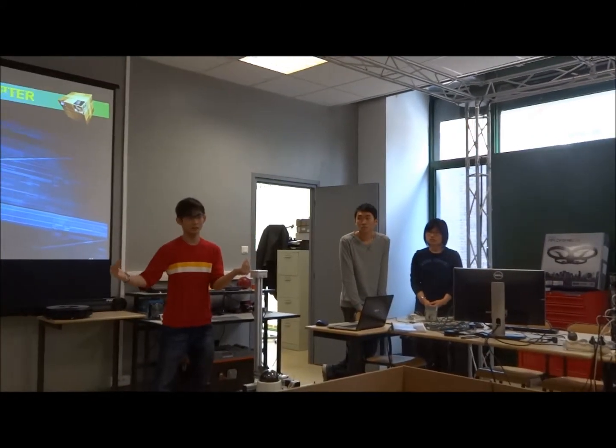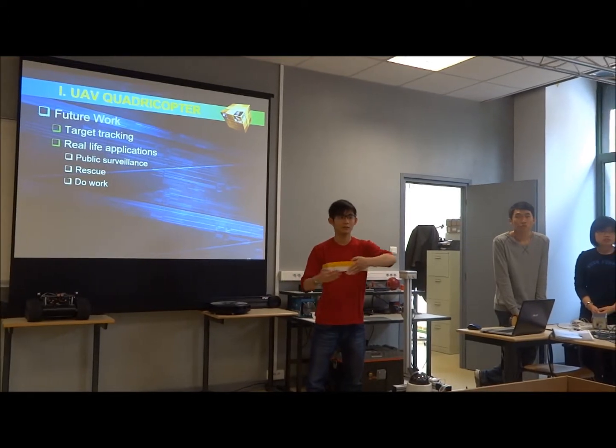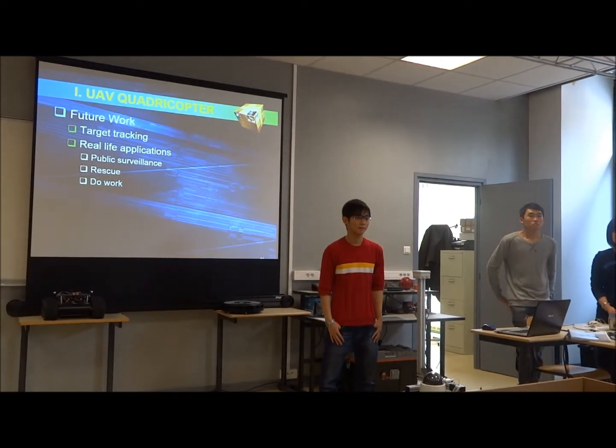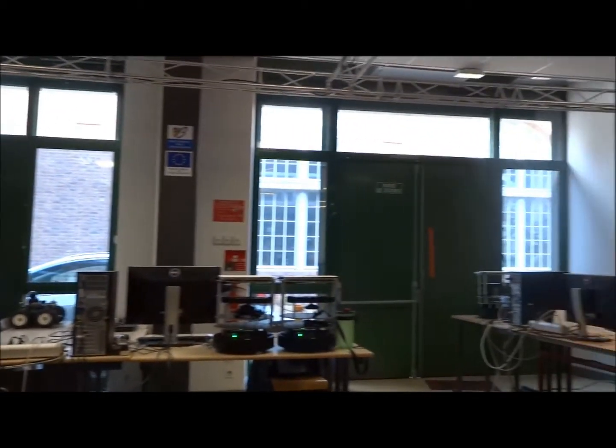Okay. Thank you. Just about the target provided by PARROT, you show some images with the distance of this target to the camera. Does the PARROT compute several positions in order to compute the distance? As long as it starts moving, then it will compute the distance. Like if you start the parrot and then you put the target in front of it, it won't actually detect. So unless you move it a little bit, or you move the parrot a little bit, once it has two locations, it can compute the stereo estimation. Thank you.